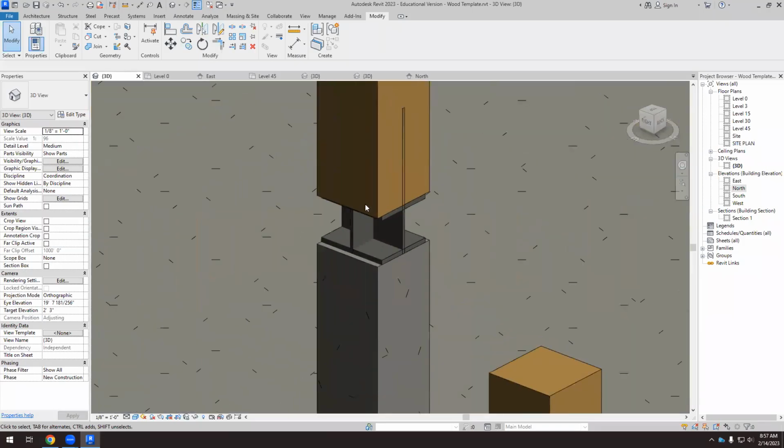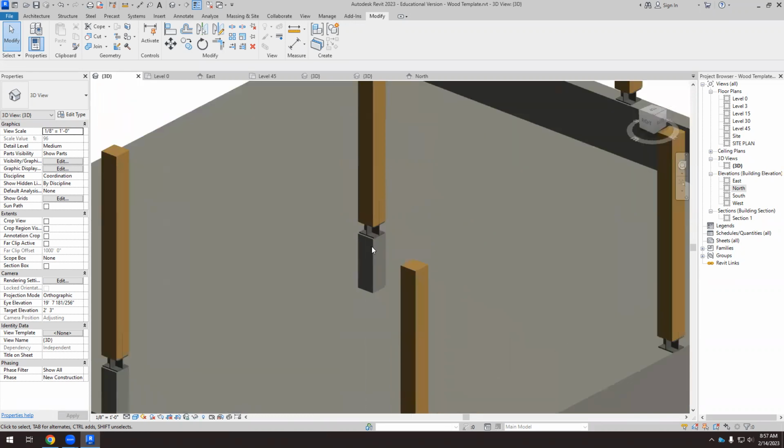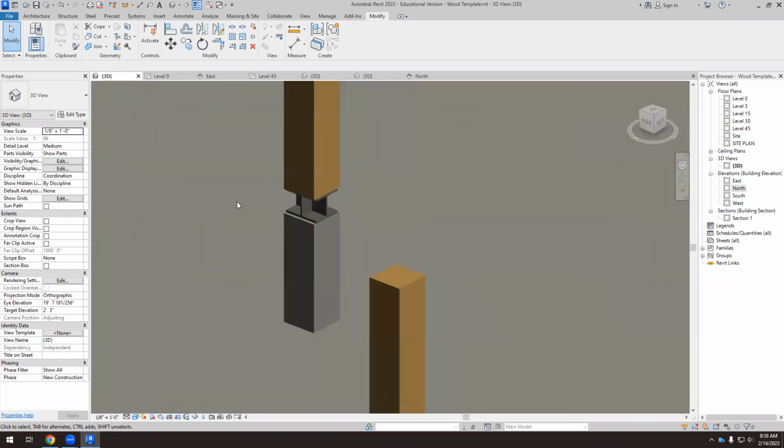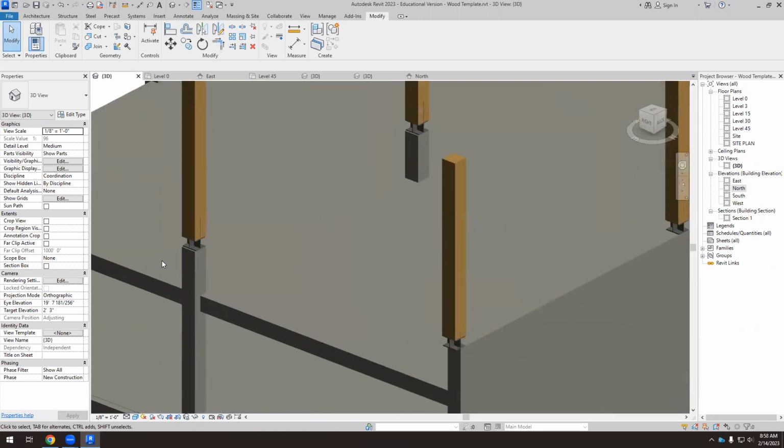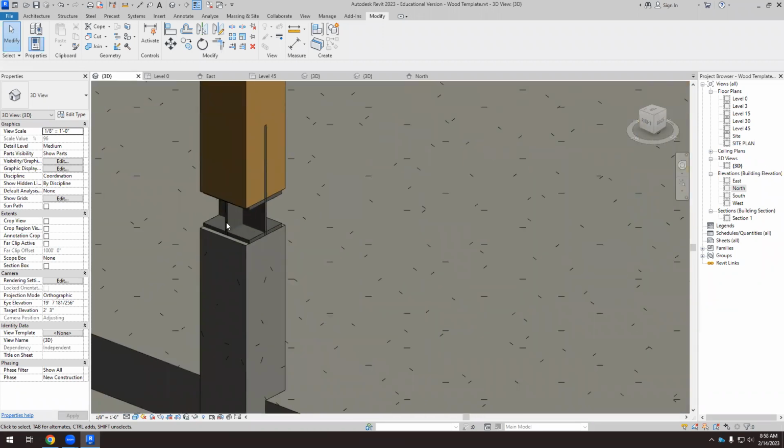You will find out that in good buildings made of wood, we always have this kind of connection. Sometimes we don't see it because we can have a flooring and we can hide this option. But I think it will be there. So the transition between the column made of wood and the slab or the wall or columns is always a metallic element like this.